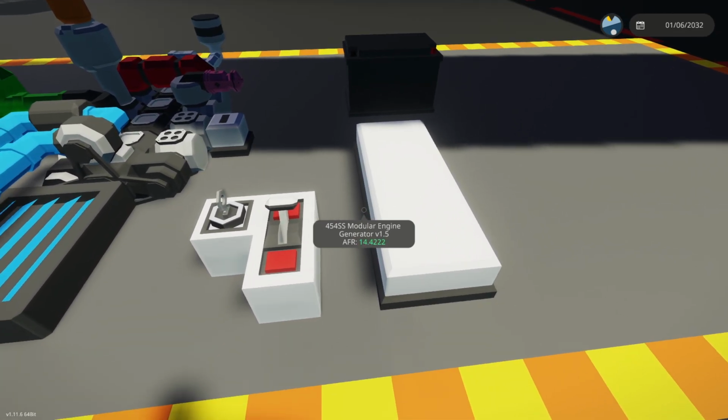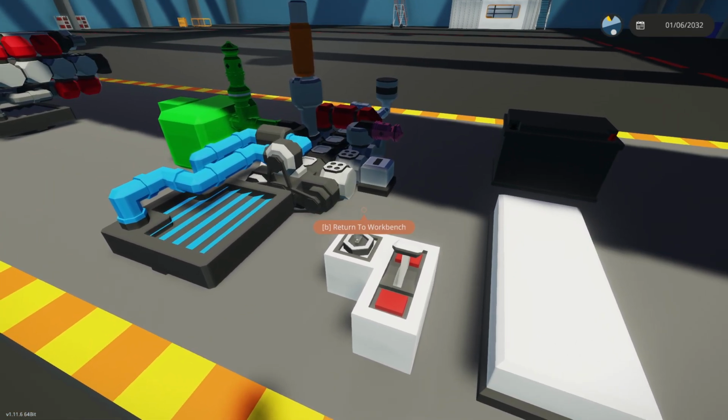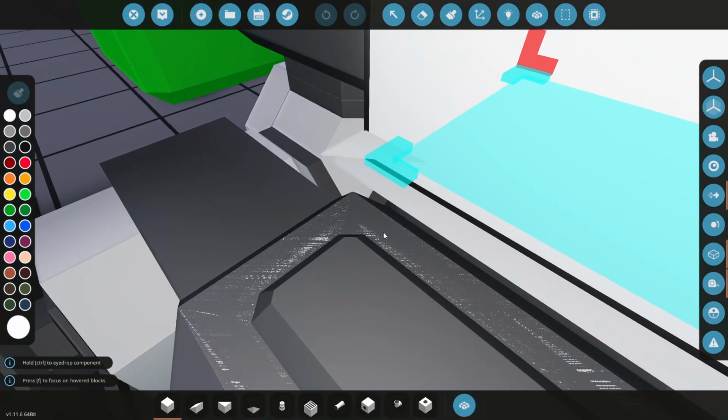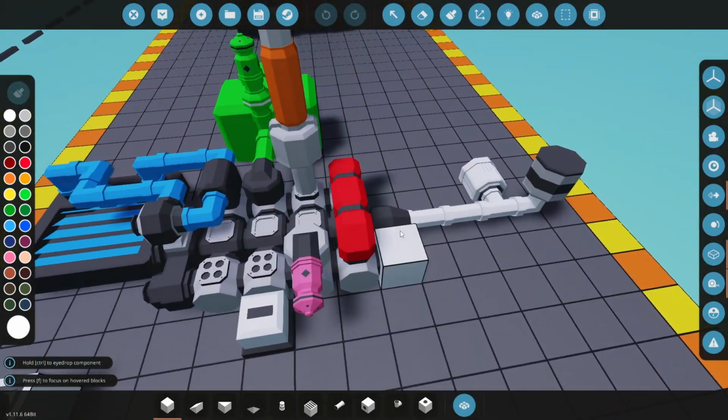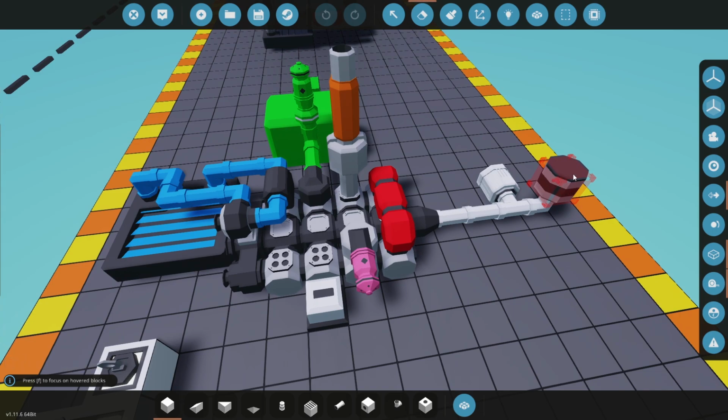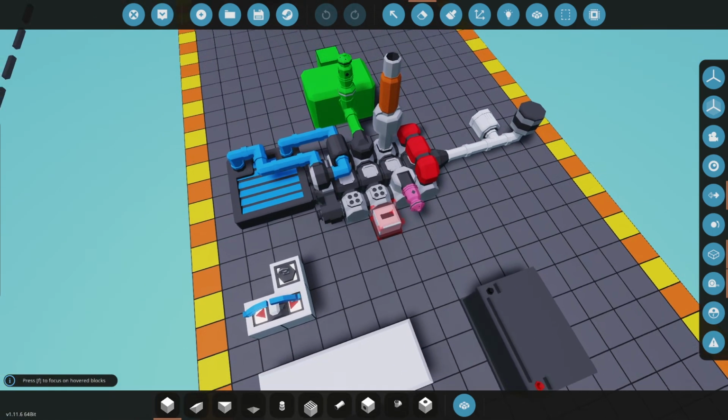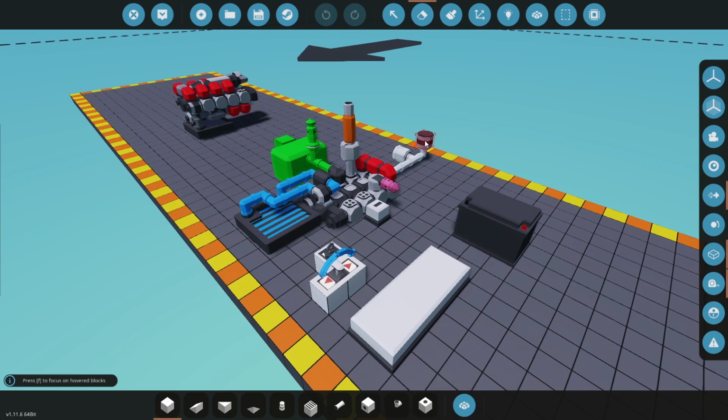Say you don't want this to be happening. Well, why is this happening? It's happening because the load on this engine, which is this generator, is way too little for the capacity of this engine. This engine is breezing right over this little generator, and it is not even worrying. So it's not at all being slowed down, in essence, by this generator, and it wants more. It wants to keep going.